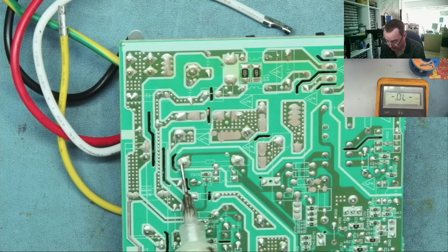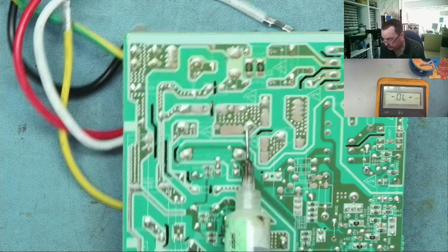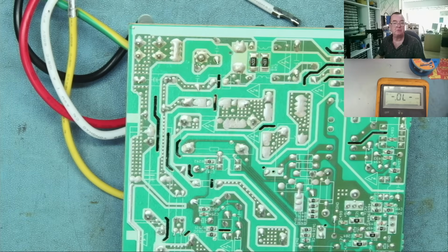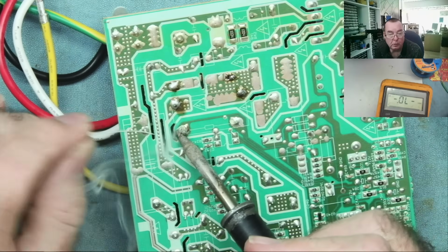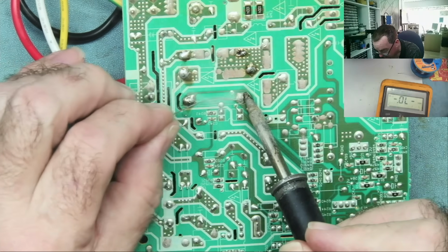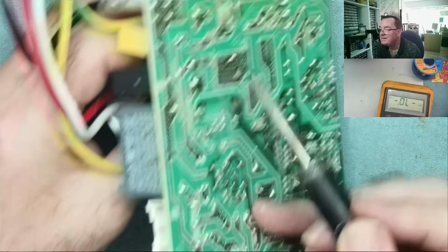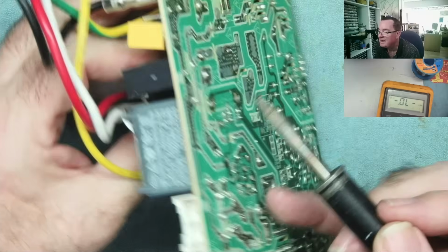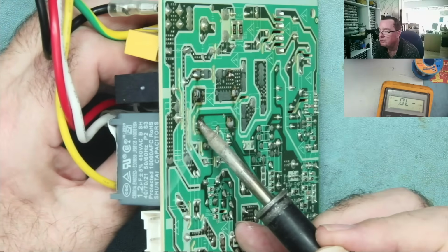We'll try this with braid. If it doesn't come off easily, we'll use a desoldering tool. Okay. Of course, I put the solder in the wrong place. Never mind. No problem. You see that? I warmed one and warmed the other, and this end just lifted out a little bit. This is another way to do it. You see it's moved.